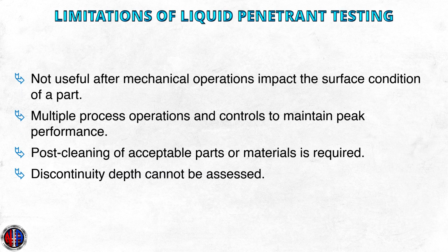It is not useful after mechanical operations impact the surface condition of a part. Multiple process operations and controls are needed to maintain peak performance. Post-cleaning of acceptable parts or materials is required. Discontinuity depth cannot be assessed.